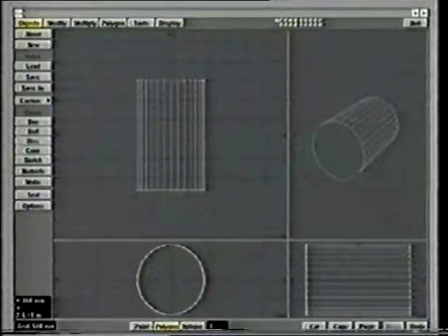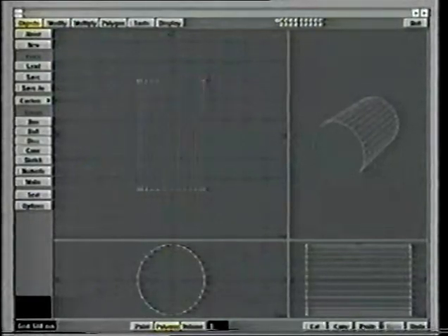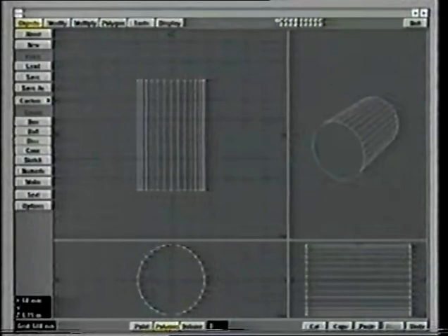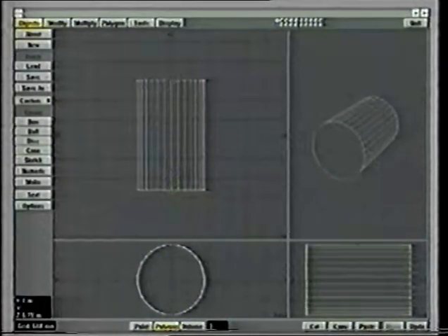So what I do here is I can cut this and paste it back in again so that the polygon itself is now detached from the other object. Like if I hit the select connected, that's it, that's the only thing it's connected to. So now when I bevel it, it's going to have a hard edge here and it won't smoothly shade across it. Sometimes if you're thinking ahead, it's a bit easier to do this than it is to go in afterwards and select those surfaces, cut them out and paste them back in again. Sometimes it's easier to do that as you go, and this will be an example of that.